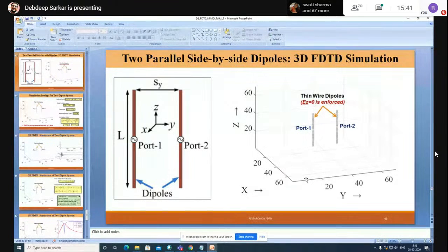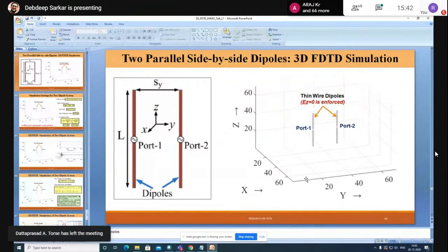So at the 6 faces we can choose 6 layers of PMLs, and some of them will be overlapping based on which edges are actually touching. Individually, those layers can be modeled to have different reflection coefficients. Also, say you know that in a certain direction there is more radiation or more flow of your signal. In that part you put more layers, in another part you put fewer layers. So I think those provisions are there. That much I can say.